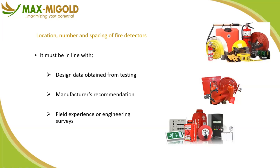The truth of the matter is, if a space is not occupied and you decide to put fewer smoke detectors there, you might actually be endangering that space, because even if there is a fire, that fire needs to build up before the smoke detector can sense or detect it, which then takes a longer time to fight. So there are a lot of dynamics in the engineering design for smoke detectors, but basically we use NFPA 13 for sprinklers and NFPA 72 for the fire detectors. Next slide, please.